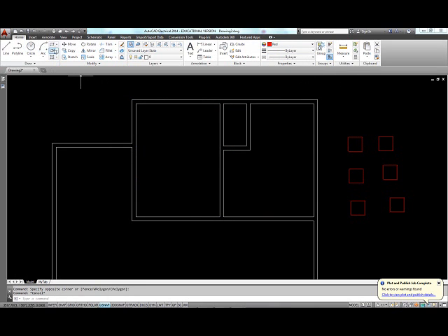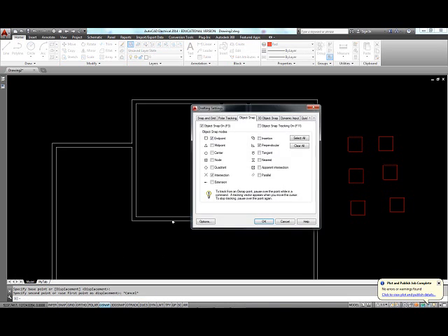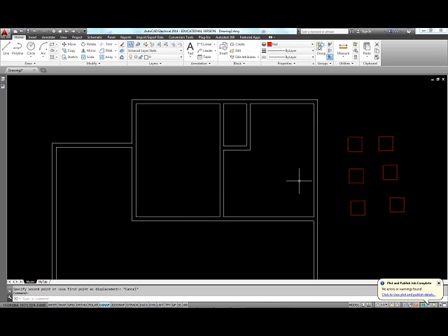And now let's take the first or one of these squares. Choose spacebar or enter. Take it from this corner. Be careful with the perpendicular snap point. It might interfere with your drawing. So I'm going to go back settings, and I'm going to take out perpendicular and just leave the intersection and endpoints. Let's just say OK, and let's do again move.